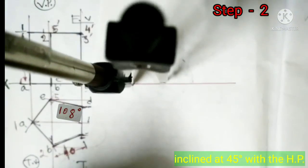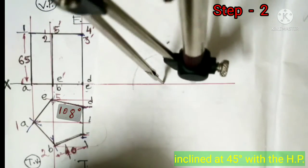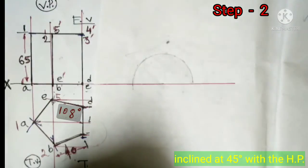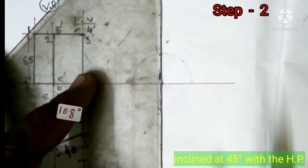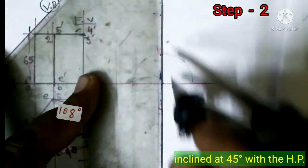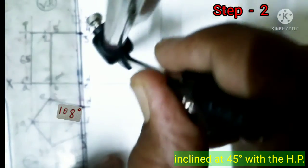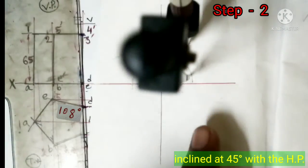To make a 45-degree angle, take any point as a center on the XY line. Make a semicircle with any random radius. Then draw the perpendicular line from this center. After that, draw two arcs, taking the end point of the diameter of this circle as a center.